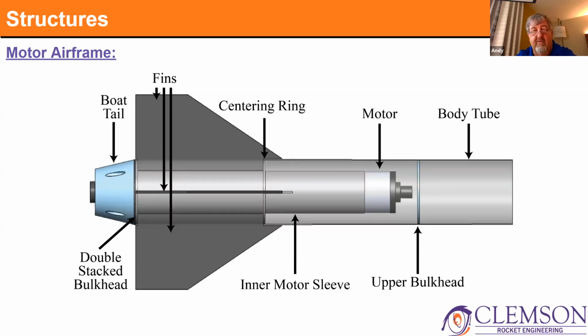And then also, with the motor casing, when you insert that motor casing into the back of that motor tube, this is Aerotech or Cesaroni? Aerotech. Okay, so the rear closure for that Aerotech motor should butt up against the rear of that motor mount tube. Is that correct?